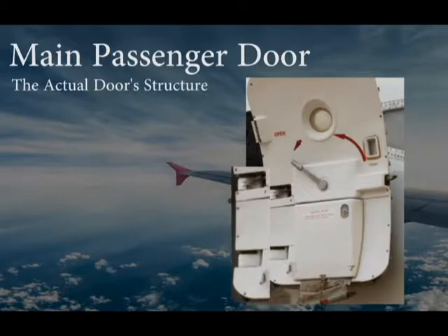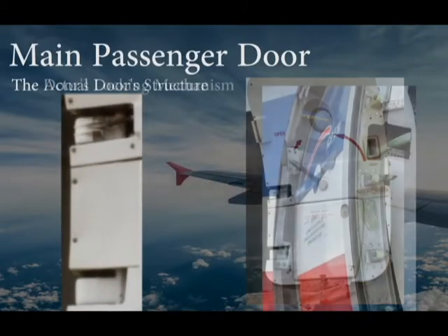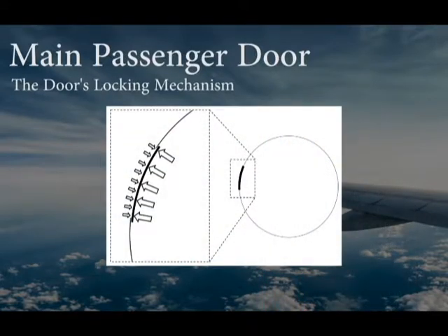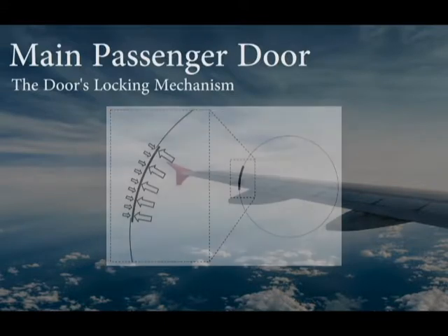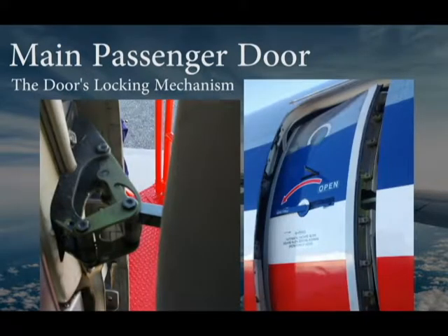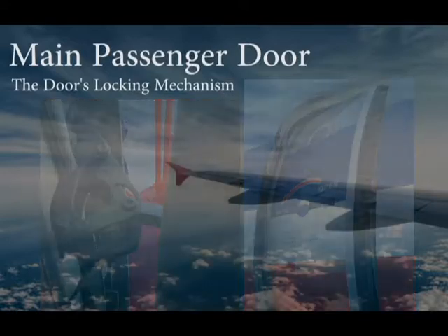Although the door does swing outward, it first pushes inward and to the side before swinging outward. This is so that when the door is closed, the pressurization in the fuselage pushes the door onto the frame of the plane, sealing the interface. This allows high pressure to help seal the door in flight conditions. Higher altitude gives higher gauge pressure. The door is supported by large hinges that allow the door to move inward, then outward, so the door may be opened in a convenient manner, while allowing it to be sealed by the pressure difference.